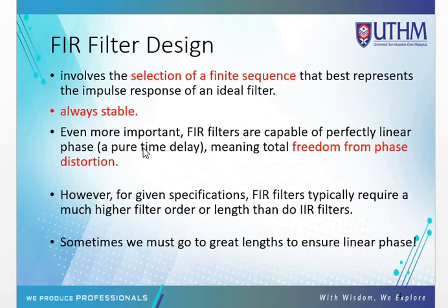This means that it's free from phase distortion. However, FIR filter requires a higher order of the filter design than the IIR filter. Somehow we need to go to the higher length or greater length to ensure the linear phase.